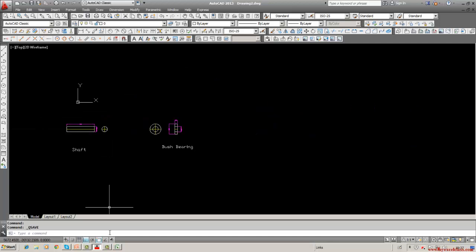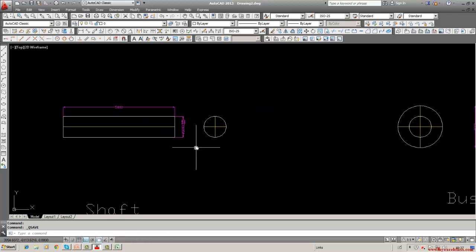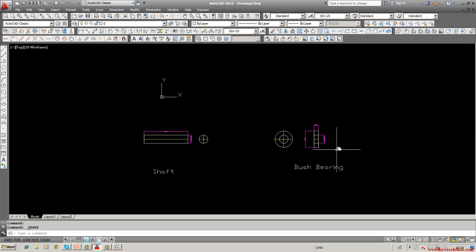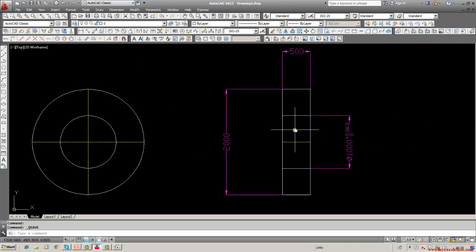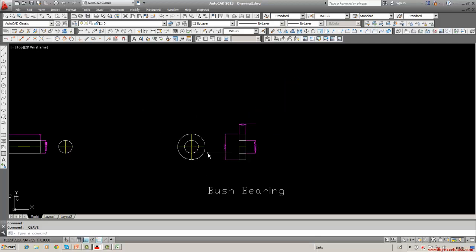But it is a rough running. So if you want very slow speed, it can run. If you want high speed, the clearance should be made very small. It can be made as small as 20 micron, 0.02 can be made. Then you have to adapt different machining processes, grinding, super finishing, some such mechanical processes. Same way for the bore also we have to adapt. Okay, this is how we can do tolerance.